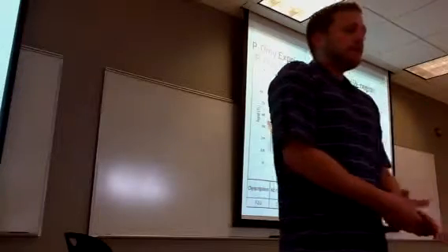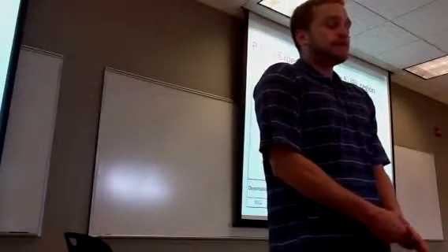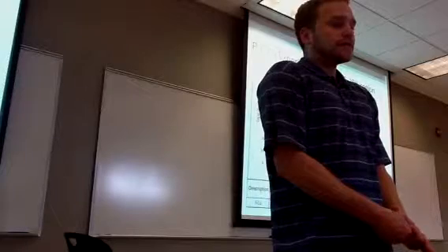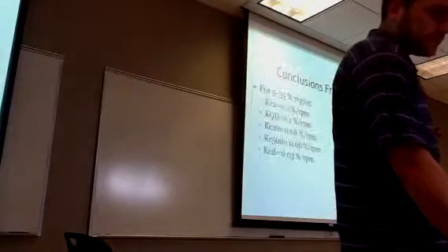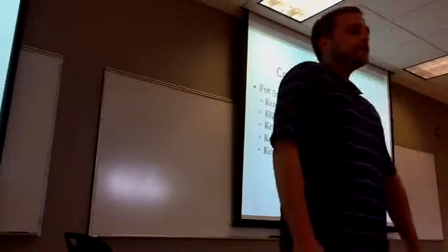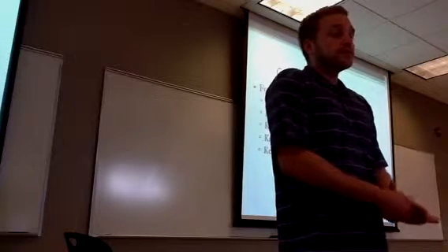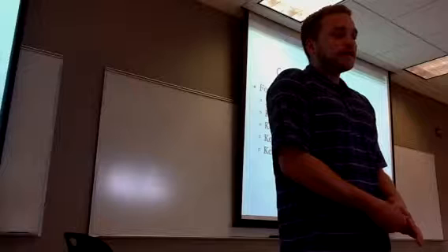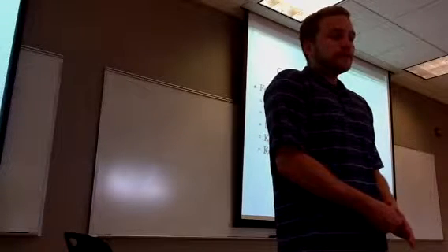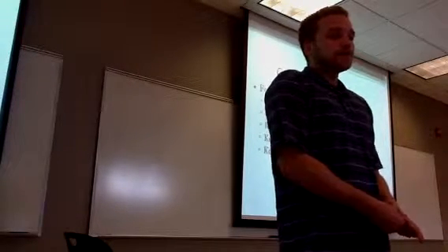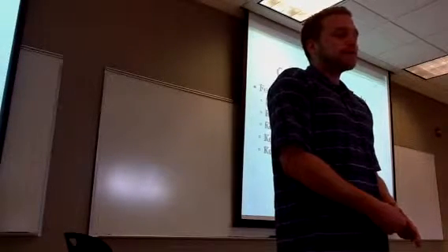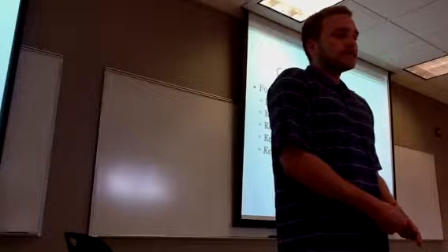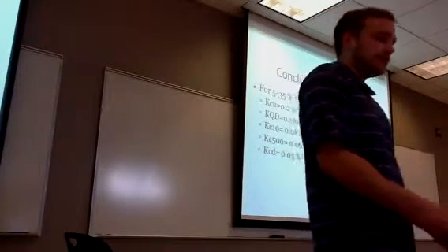Here it is with the ultimate gain, where the controller gain is 0.2% per RPM, and it's oscillatory with a frequency of 2.875 hertz. The conclusions from the proportional only design are that the KCU is 0.2% per RPM, the quarter decay is 0.1% per RPM, the 10th decay is 0.08% per RPM, the 1/500th decay 0.06% per RPM, and the critical damp decay is 0.03% per RPM.